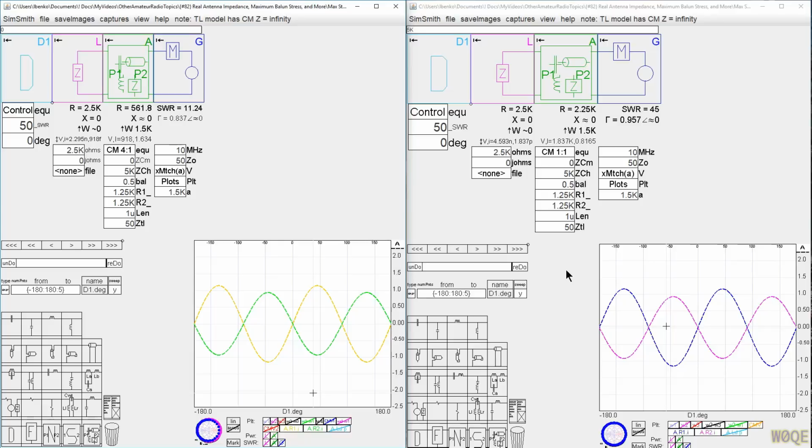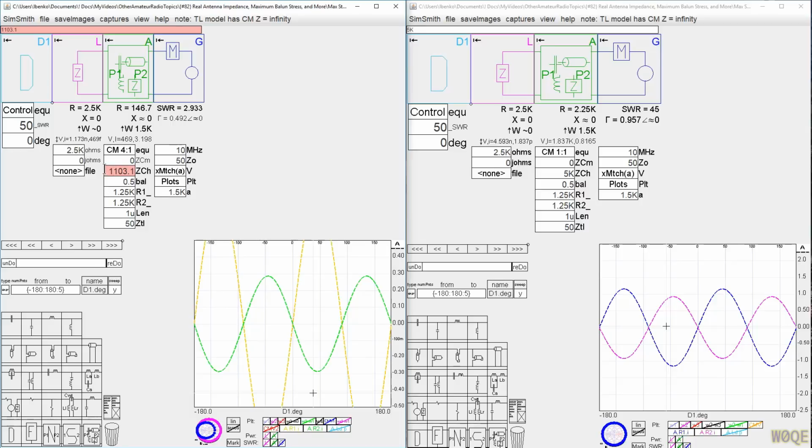If you think about what 1 picofarad is at 30 megahertz, it's about 5 kiloohms. An imbalance of 1 picofarad somewhere in your circuit undoes that. In this case, the choke is just the choking impedance. But if we were to build a circuit that we tried to make balanced on its own merit, the Johnson matchbox was never a very good balance. I measured the output currents on the Johnson matchbox, and they're not matched this well at all. But for most cases, that doesn't matter. It's picked like, say, 1 kiloohm.